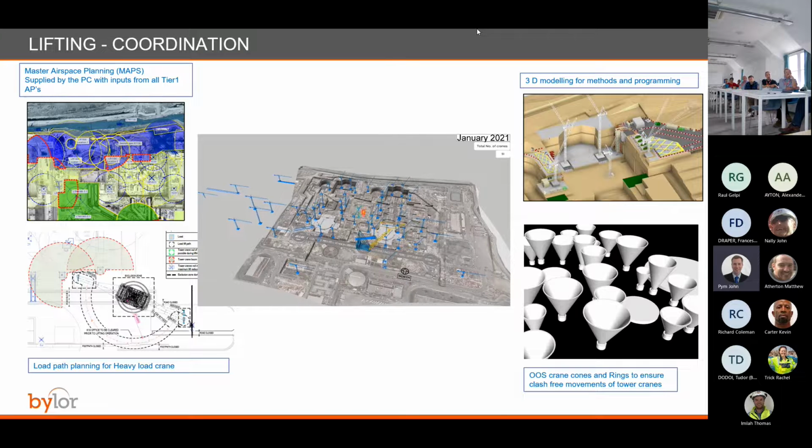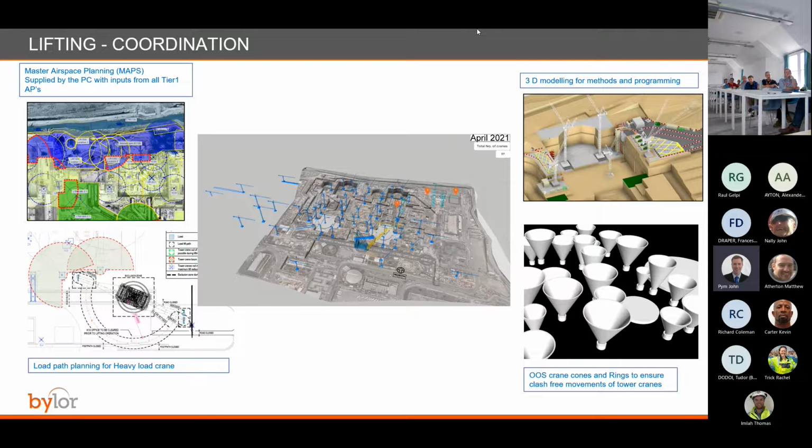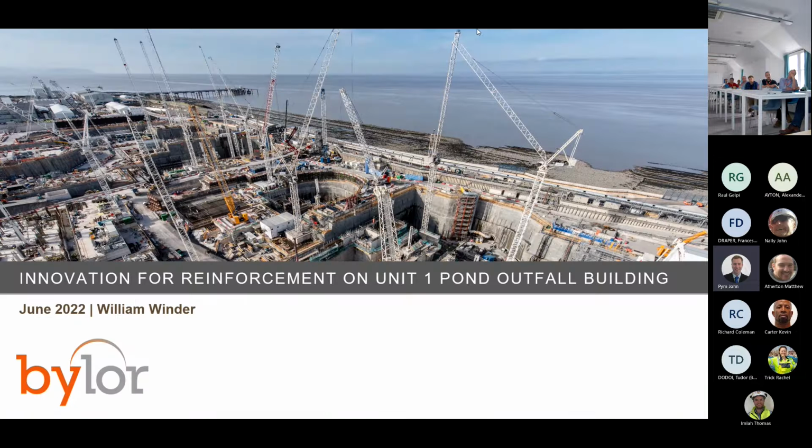So they have to spin in cone shapes like you can see in the bottom right-hand corner there, or discs if they're a flat top. They always stay the same radius. So we have to do a model like that to check any new cranes. This particular model was done years ago as we started HPC, but we have new cranes coming in, a couple in the last year, in fact, brand new ones that weren't considered. We have to make sure that they're not going to clash when winds blow at night time and there's no operator that can control them.